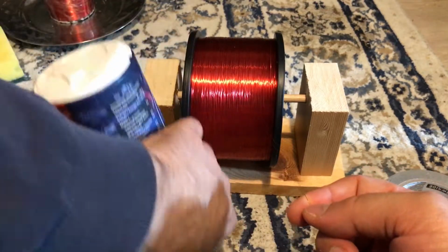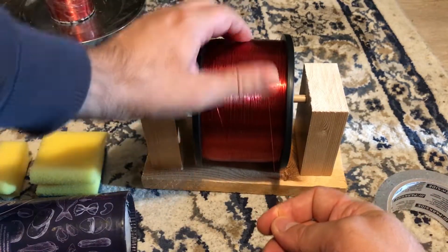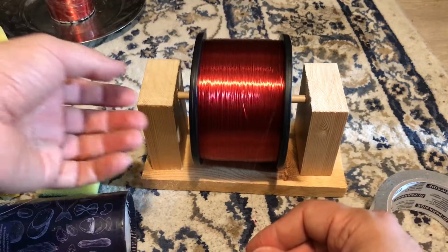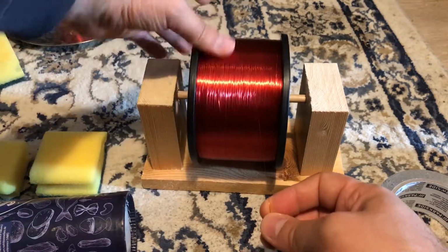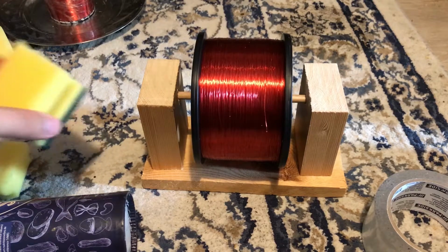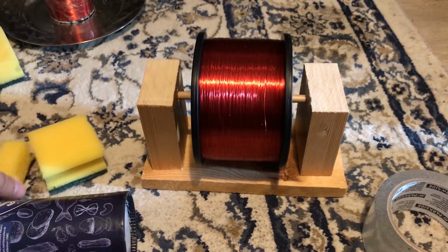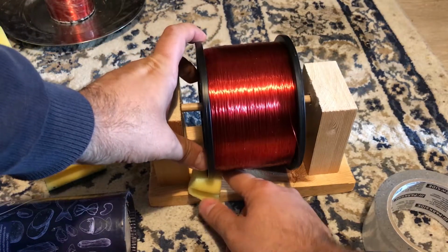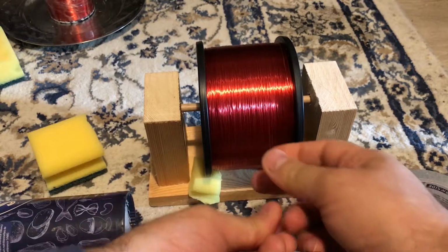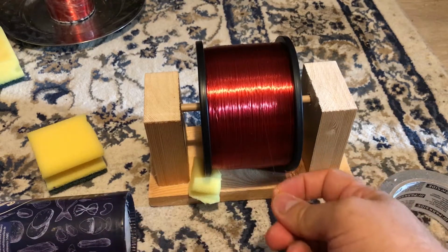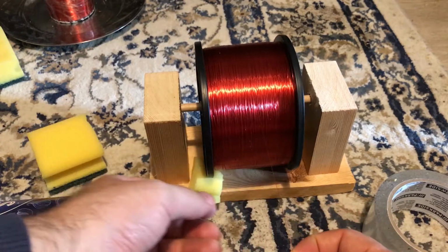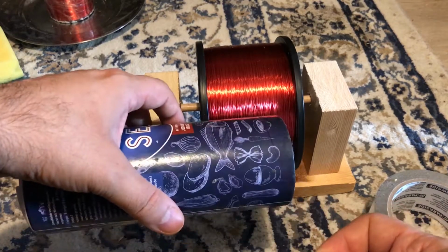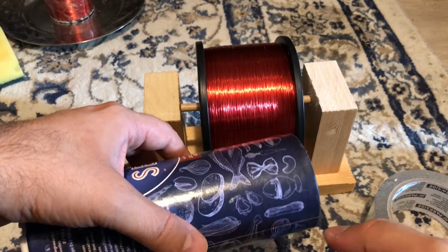Now when we make the secondary coil, we want to have a constant tension over this wire. In this situation it doesn't have that, so at every moment it has a different tension. In order to create a constant tension, I did some innovation. I took a piece of sponge and cut a little bit of it. Now if you place this piece of sponge under this reel, when you drag and pull the wire, the reel will always feel a constant force on it, so there would be a tension on this wire. In that case you can make a very nice and compact coil.